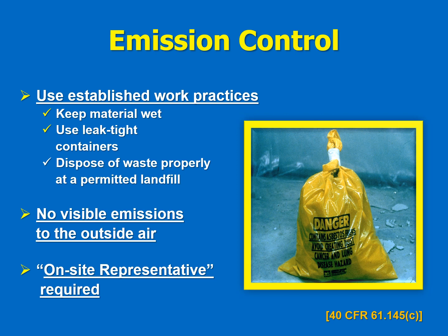Emission control is another integral part of NESHAP. One of the main mantras for NESHAP is no visible emissions. In line with that, the contractor must use established work practices to keep the material wet, to use leak-tight containers, and to dispose of the waste properly at a permitted landfill. No visible emissions to the outside air, and an on-site representative, such as an accredited asbestos supervisor for the state of North Carolina, will be required on such jobs.